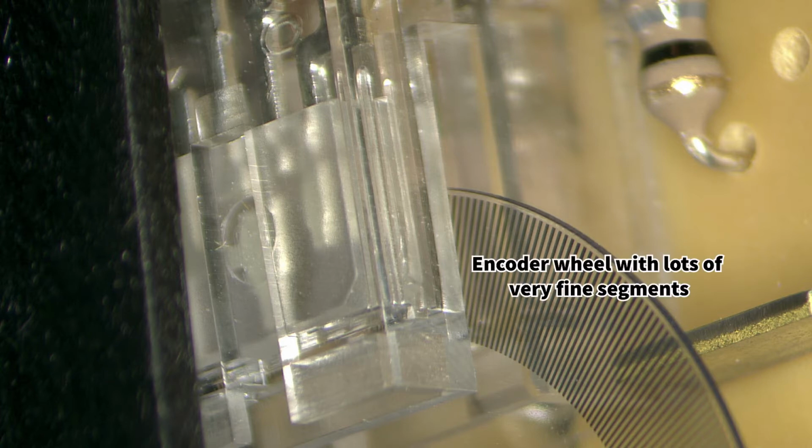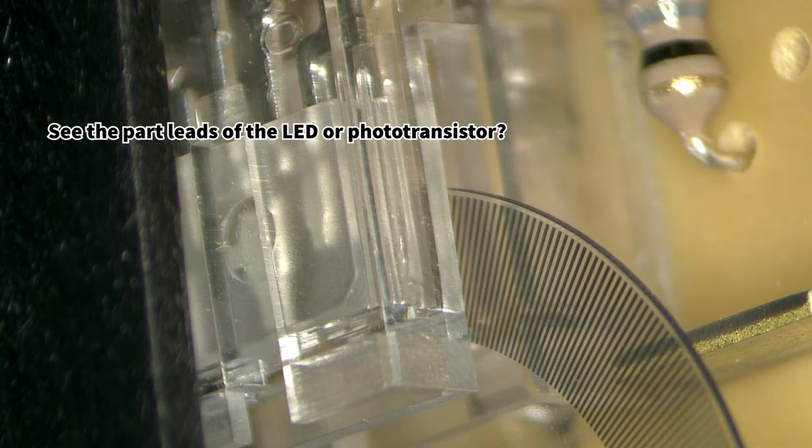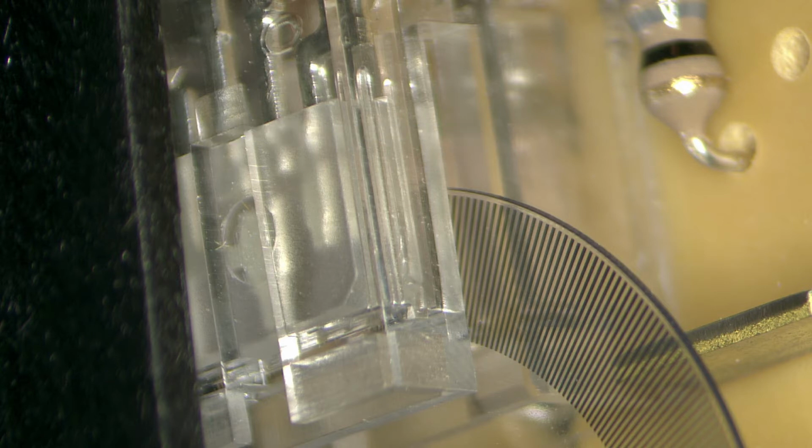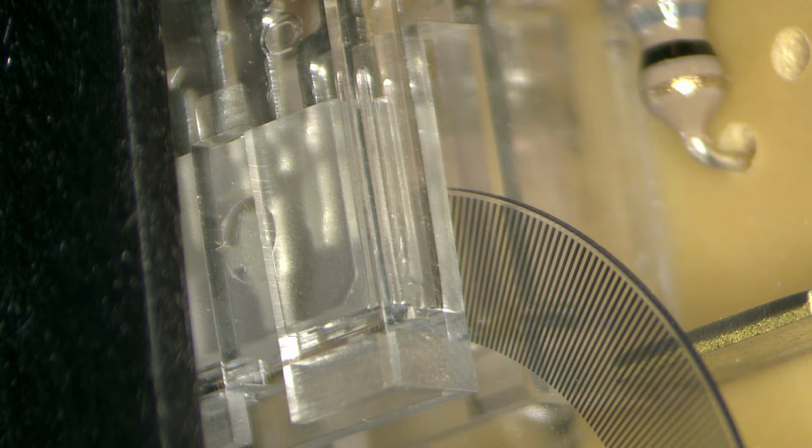On one side it'll have a light emitting diode, usually an infrared one, and a phototransistor on the other side. So these little wedges, I guess you call them, segments along the outer edge of the disk, will interrupt in a certain pattern so that the computer monitoring the encoder will be able to figure out not only its position over time, like it'll count how many ticks, but it'll also know the direction based off of the position of these two sensors. It'll also be able to determine everything from your velocity and acceleration. They're used in lots of other things, but those are fairly the most common ones.